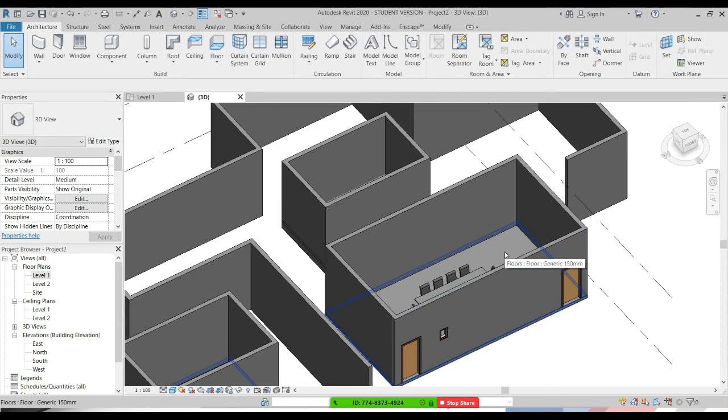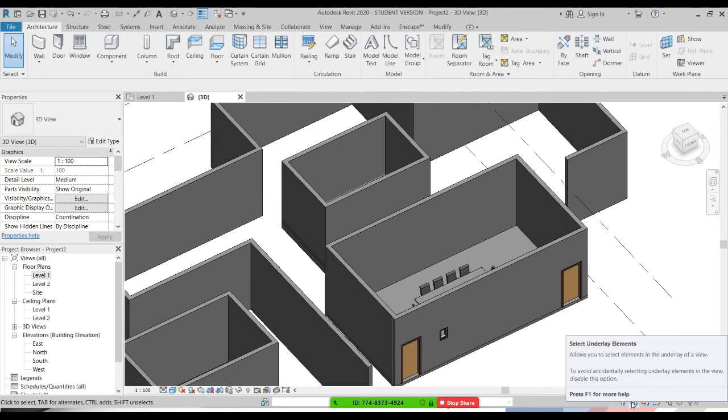When you're selecting the floor, you've got that arrow on the top of the floor. When I do that, it doesn't select. I have to go to the base of the floor. Perfect question. Thank you so much for the question. Okay, this happens because of these selection filters. Can you see the bottom right corner? This is what I like about questions, guys. You know, each one will teach us something when they ask a question.